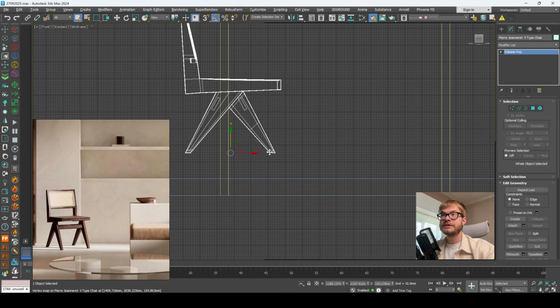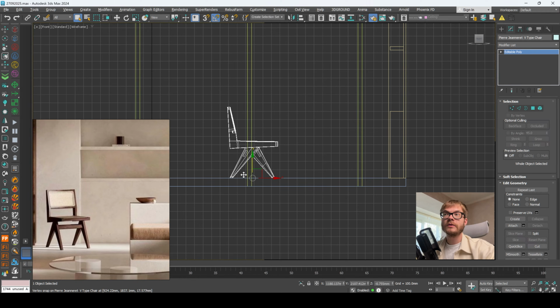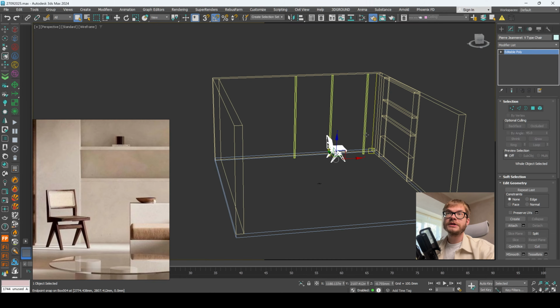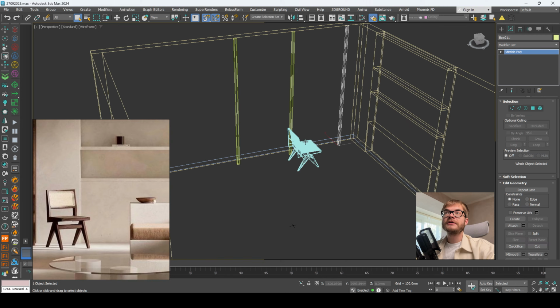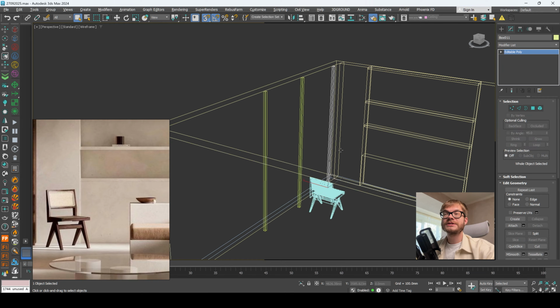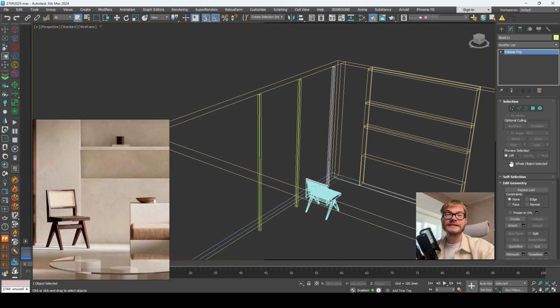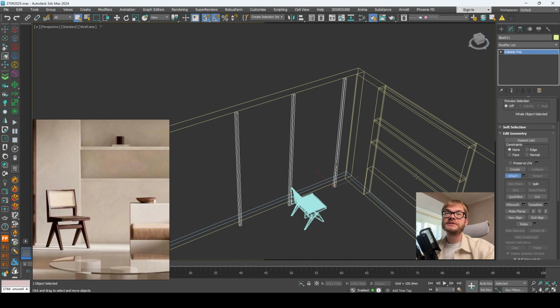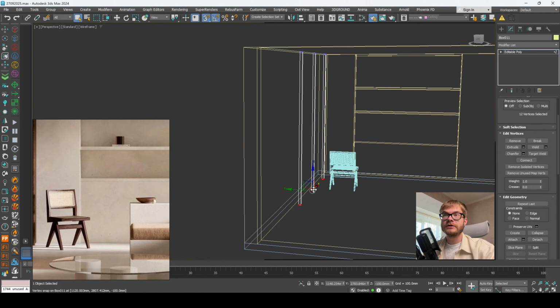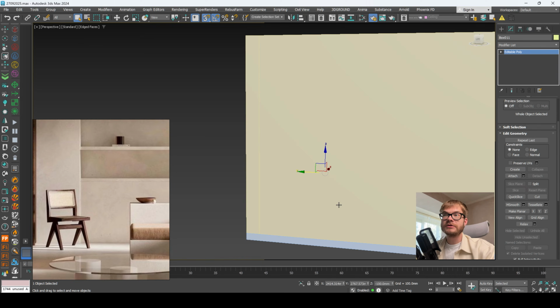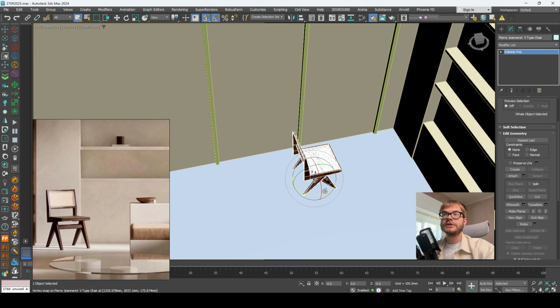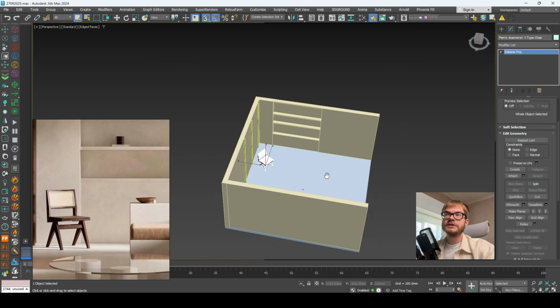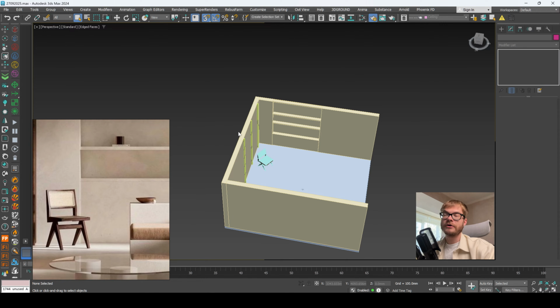Press F6 to enable only Y-axis mode, and here I can see that our planks right here go into our floor. Let's also fix this and attach our details using editable poly mode. Now select our dots and paste it right here. Now select our chair, rotate it. Let's continue to paste other parts of our model.